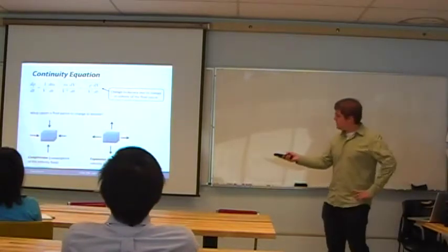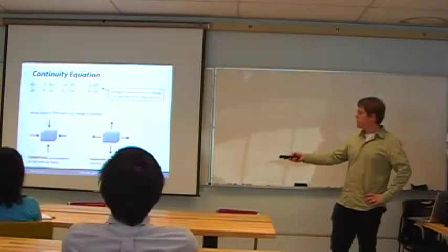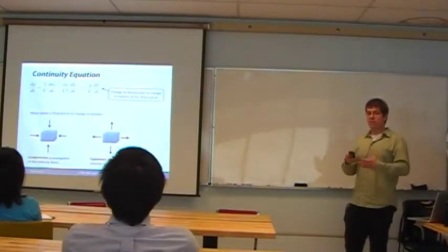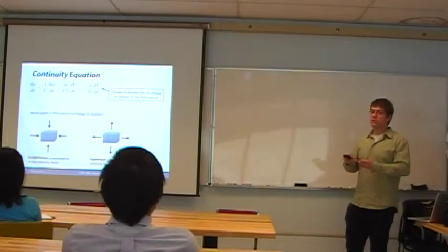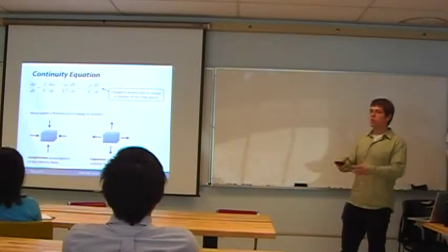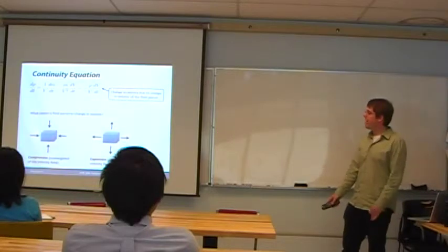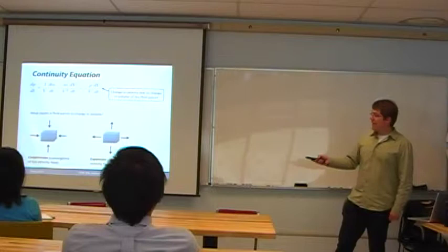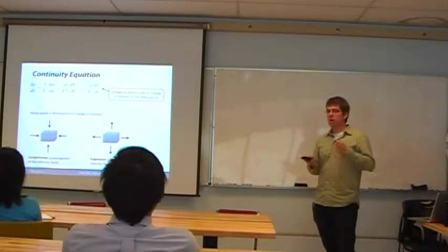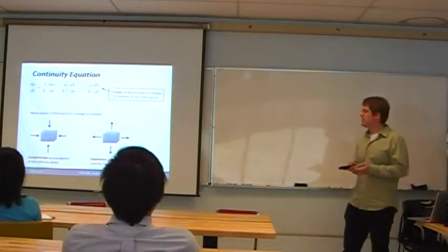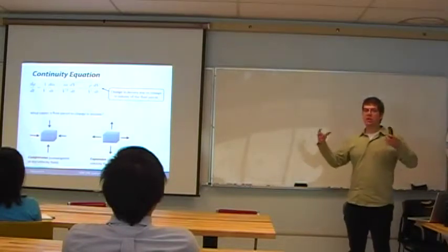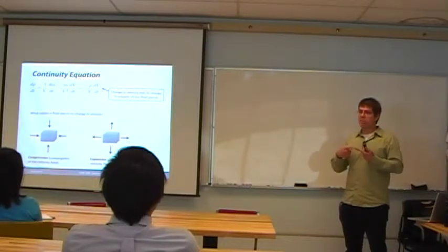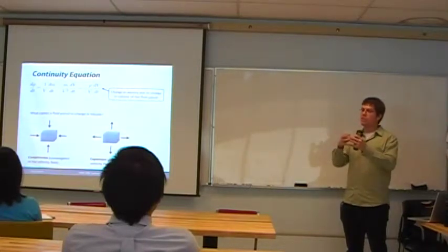And since we're dealing with compressible fluids, namely air, we're able to actually observe this. So compression and expansion. Compression of the fluid parcel will cause a negative change in the volume of the fluid parcel, so the volume will shrink with respect to time. Expansion will cause the volume of the fluid parcel to expand with respect to time. And compression, we can relate back to what we already know of the state variables, namely the velocity field, by saying compression is caused by convergence of the velocity field. If we have a bunch of velocity vectors all pointing into the same point, then that's basically compression of the fluid, right?